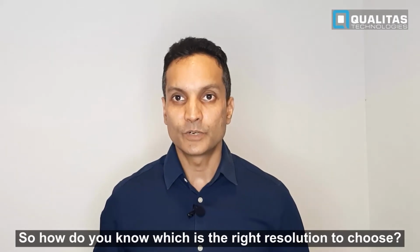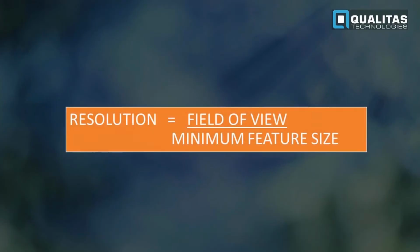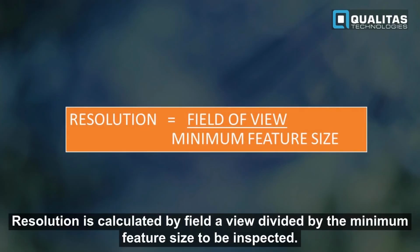So how do you know which is the right resolution to choose? Resolution is calculated by field of view divided by the minimum feature size to be inspected.